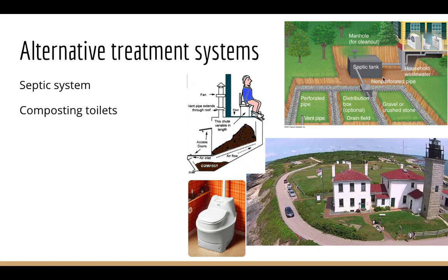This septic tank also has bacteria in it that are digesting some of the stuff that has settled out. But you do get accumulations over time. That's why if you have a septic tank, you have to get it pumped every once in a while. In order to maintain this system, you have to be careful of what you dump down the drain, because some stuff can clog the tank, or it can kill bacteria that are in the system. You want the bacteria there because they're breaking down the waste. So you need to inspect it regularly, and you need to pump it regularly. Oftentimes you can have your garbage disposal go into this septic tank, but if you do, you're going to have to pump it a lot more frequently. And you obviously don't want heavy equipment on this leach field because that would destroy it.